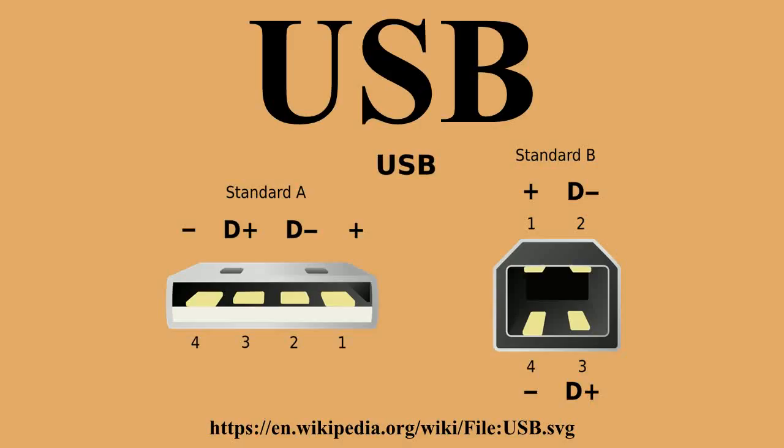Device classes. The functionality of USB devices is defined by class codes, communicated to the USB host to affect the loading of suitable software driver modules for each connected device. This provides for adaptability and device independence of the host to support new devices from different manufacturers.